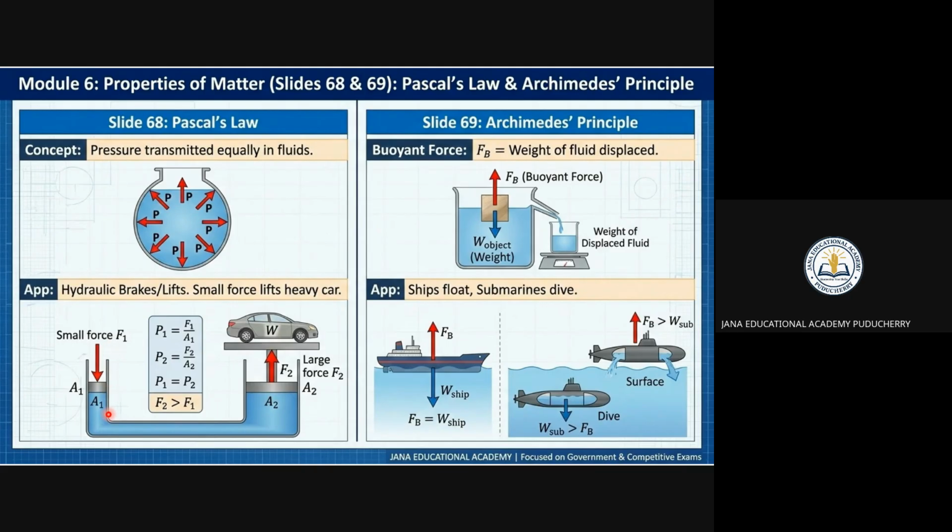A small force is applied here, and you can develop a large force by using that, right? It is one of the important points of Pascal's law, in hydraulic braking and lifting. The small force on a small area produces a large force on a large area. It works only on confined liquids. The applications are hydraulic brakes, hydraulic lift, hydraulic press. It applies to liquid only. The pressure is the same in all directions. You have to keep it in mind, right?